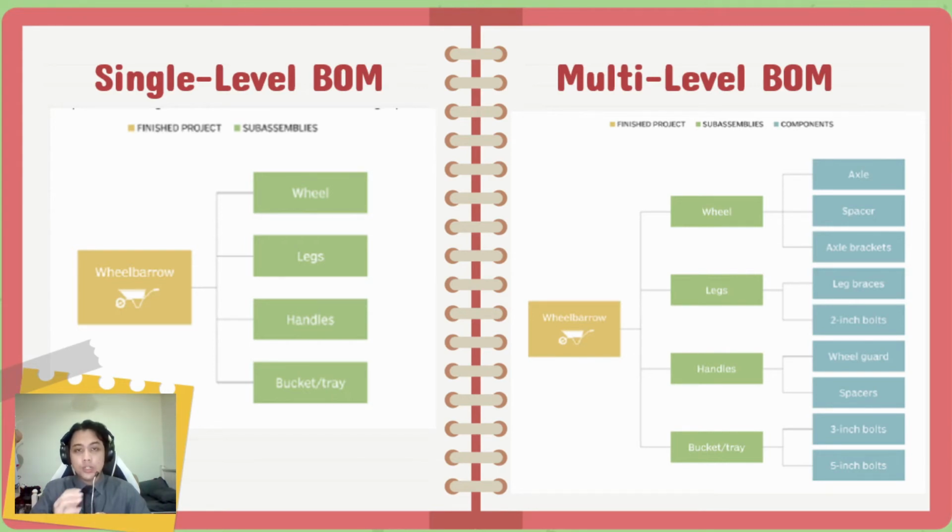It is important to create an accurate bill of materials because it ensures that parts are available when needed and that the manufacturing process is efficient. If it is not accurate, it can cause production to halt, which will increase the operational cost, as we will waste time locating the required parts, and we might need to start another production order.